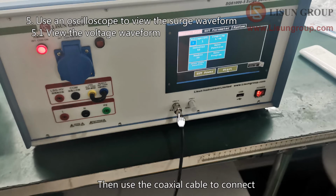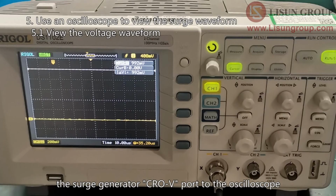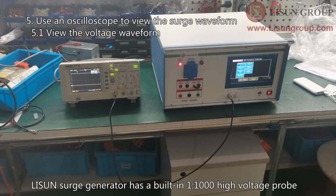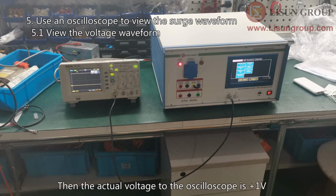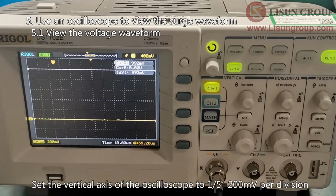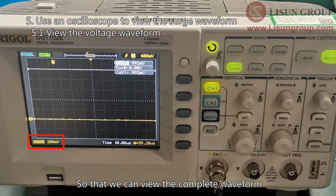Then use a coaxial cable to connect the surge generator CROV port to the oscilloscope. Builtin surge generator has a built-in 1 to 1000 high voltage probe at the oscilloscope interface. We set the surge voltage to positive 1 kV. Then the actual voltage to the oscilloscope is 1 V. Set the vertical axis of the oscilloscope to 200 mV per division so that we can view the complete waveform.